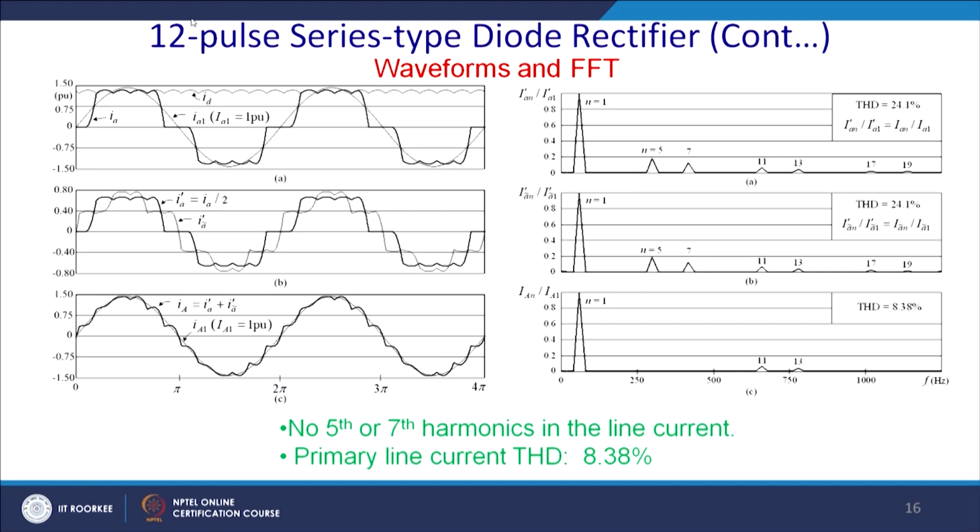So, what happened here, you will find why it is 12 pulse, because there will be two currents: this is the current for delta and this is the current for star, and thus it makes out to be the star and delta, and ultimately you will have a total of 12 pulses in the system.